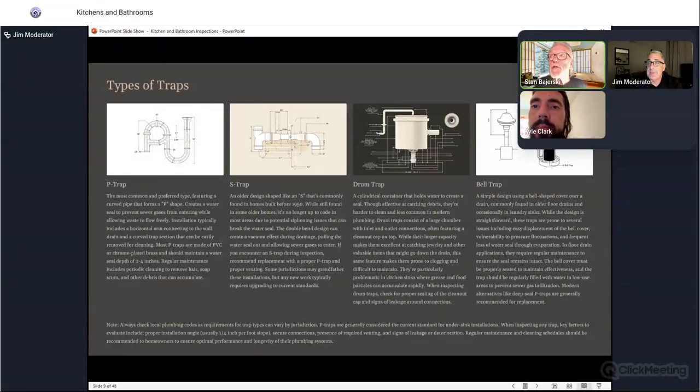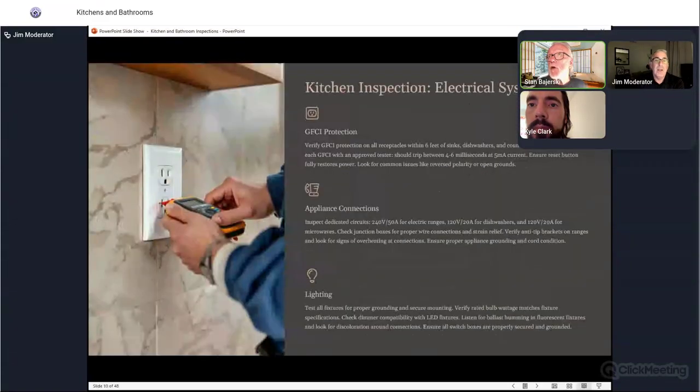Unless you're digging into the walls and changing, because think about it, the S trap goes through the floor of the cabinet into the basement, right? You have to reconfigure that whole thing and dig into the wall to be able to put a P trap. You could put a Studor vent though, right? Yeah, but sometimes it's not going to happen. And your statement about consulting a plumber would be the proper way to go. Yes, right? So if they can do it, they'll do it. If not, you put the water in the S trap and you live happily ever after.